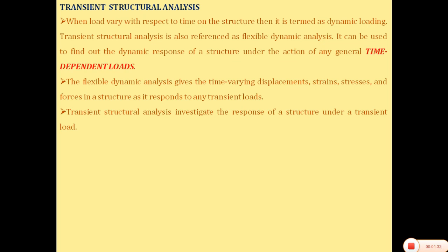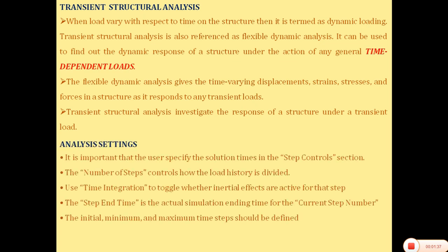Transient structural analysis investigates the response of a structure under a transient load. So these are very important things which we should know. Now while solving this transient structural analysis, we have to give some inputs in the analysis settings. While solving static structural analysis, we need not give any analysis settings, but here there are a few terms which we need to know: step control, number of steps, time integration, then the step end time as well as the time steps. We will see all this when we actually solve the problem in ANSYS Workbench.